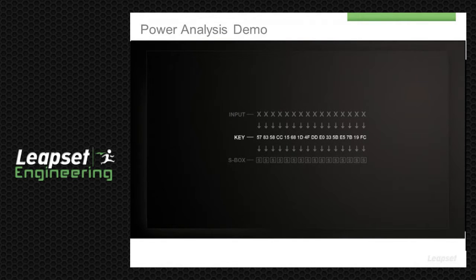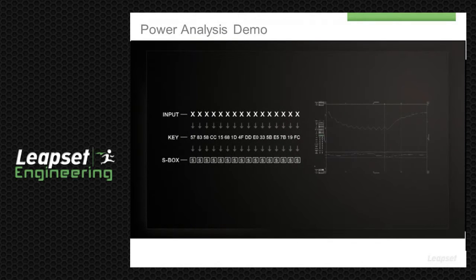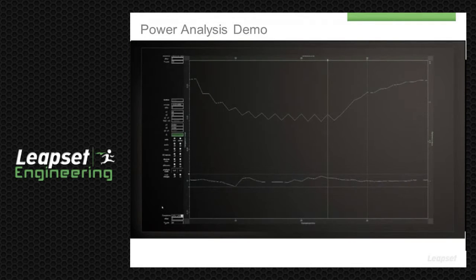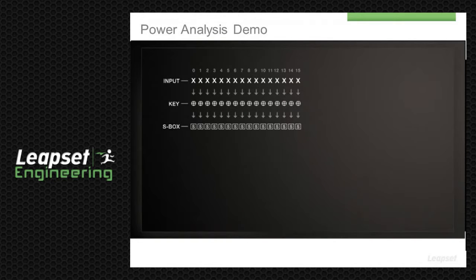If we guess 8 bits of the key and we know the 8 bits of input, we can predict the other variable, and we can correlate it against the 10,000 AES operations and the 10,000 corresponding ciphertexts. If the key guess was wrong, then the values being predicted are not related to anything that's being done within the FPGA. So there will be little to no correlation between the predictions and the power traces. If our key guess is correct, then the FPGA will process the correctly predicted intermediates, so the power traces should correlate with the predictions. Here we are predicting the 8 bits that go into the 15th SBox table lookup.